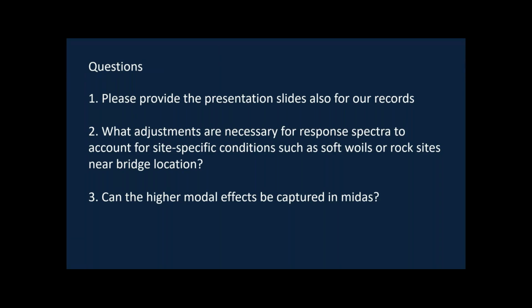So third question, can the higher modal effects be captured in MIDAS? The answer is yes. Depending upon the number of frequencies that we suggest to the program, the higher modes are also considered. Currently, as you've seen, the number of frequencies has been limited to 50, and thus the number of modes that we have considered is only 50, and the results were seen on that basis.